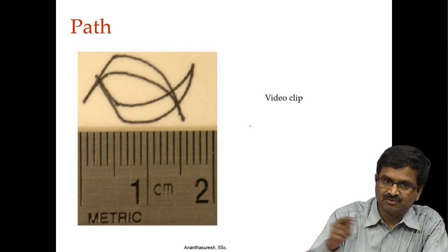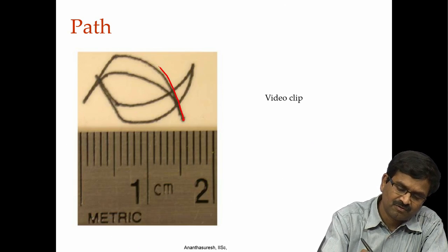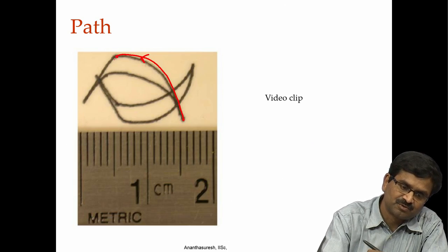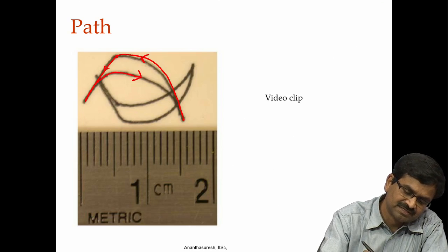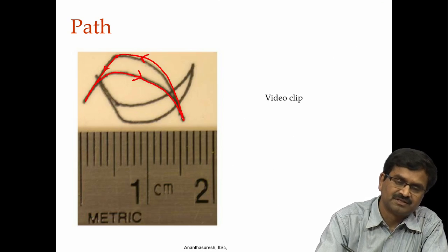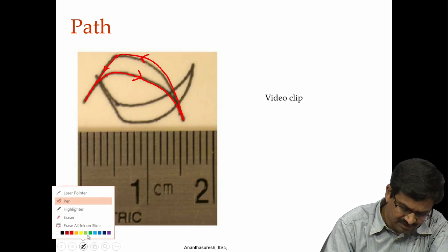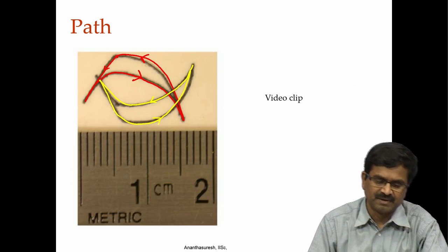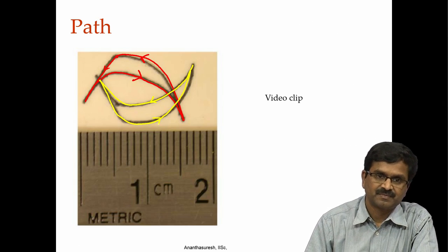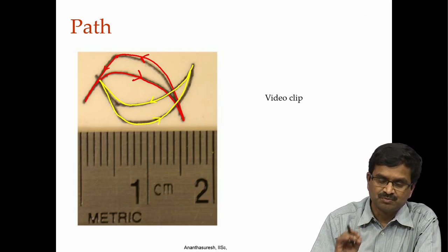In the simulation we had seen, that did not take into account viscoelasticity. What will happen is the point will start here, will go like this, and this is the non-smooth point, it will go there, and then while coming back it takes a different path because of, in this case, the viscoelastic nature, it will go like this. So, we get enclosed paths like this. The other one, let me do with a different color. So, it goes like this and then comes back like this, like banana shaped curves or chili shaped curves. Okay. So, it is possible to get a non-smooth response even though you have a smooth input.